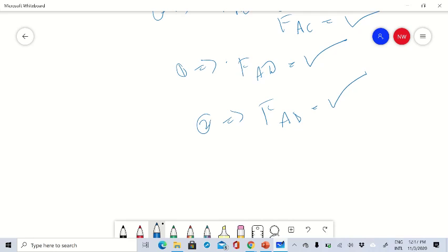So we have found the force FAB. We know F is equal to K times S, right? So we know the FAB force, we know the value, and we know the stiffness constant is 500. So then we can find the stretch S, right? So we'll get the value for S, right? So likewise, we can solve particles which are in equilibrium by subjecting to forces in a three-dimensional system, right?